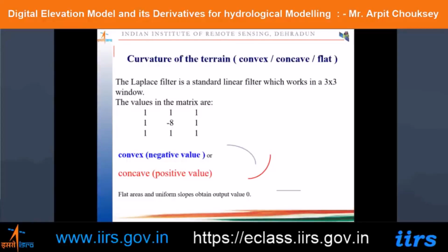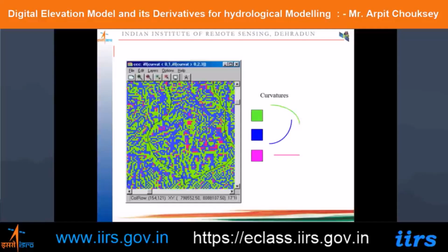And for the same contributing area, CTI is higher for the pixels with lower slope. Why? Because the tangent of beta is low, so CTI will be higher, where the flow accumulation remains constant. This means CTI primarily reflects the accumulation process. So where low slope area is there, flow accumulation tendency is more.